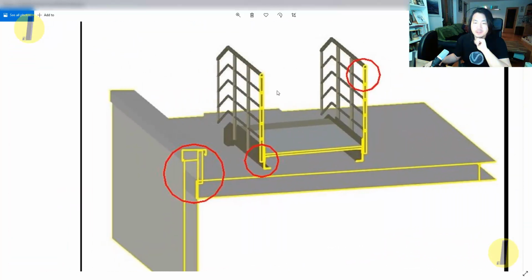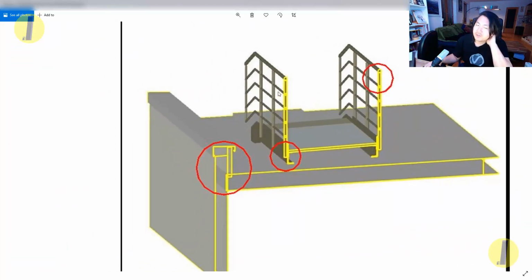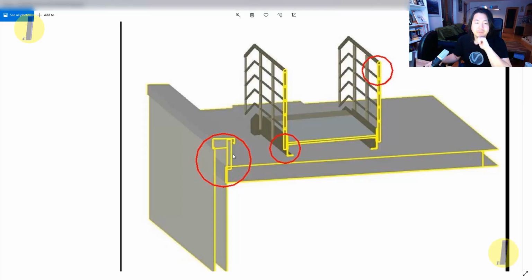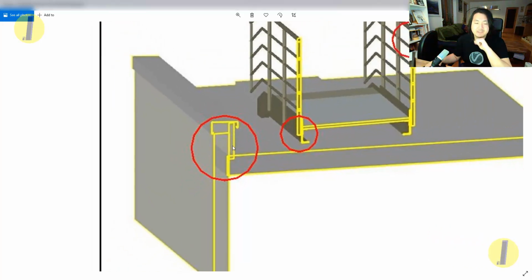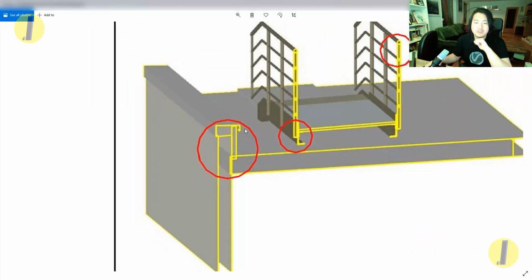So the next one is about architectural detail. Of course your model can go beyond LOD 300, or let's say LOG, level of geometry, because I'm talking here more about geometry. If the connections or architectural details are really well modeled up to LOD 400 status, then maybe you can check clearly whether there is a collision between the architectural elements or not.